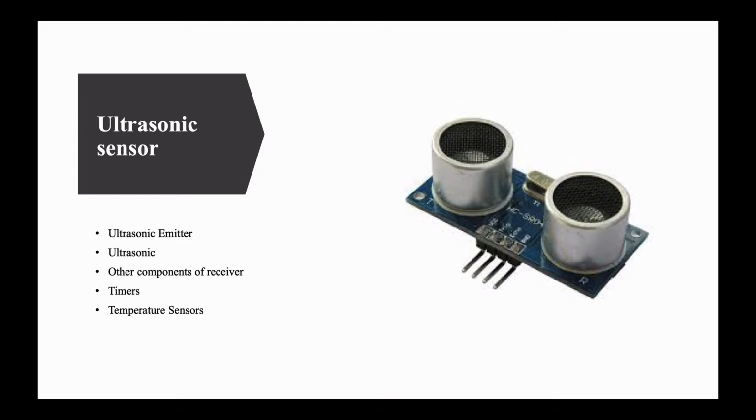Generally, a vehicle's ultrasonic radar is mounted on the car's bumper. It is mainly used for close range and low obstacle detection, to avoid the blind area of close range perception around vehicles. Ultrasonic waves can be emitted directionally, have good direction, are easy to control in intensity, and do not need to directly contact the measured object.